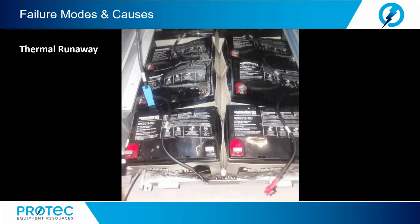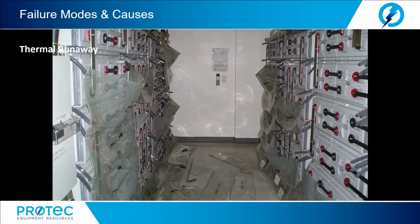Flooded cells allow gas to escape, whereas valve-regulated lead acid recombines oxygen and forms water. The recombination of oxygen at the negative plate in a valve-regulated lead acid battery is a chemical reaction which produces heat during the recharge process. Thermal runaway can be caused by overcharging, high ambient temperature, low airflow, or high float voltage. Now, internal ohmic values will increase, as will float current, before thermal runaway occurs.